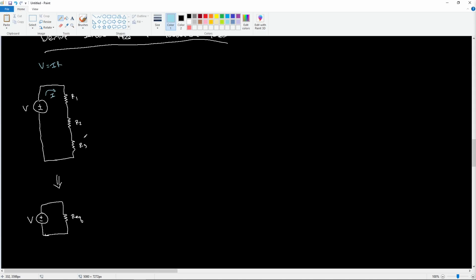And so if I think about conservation of charge, if I have just one loop that I can work through, the current flowing through this resistor should be the exact same current that flows through this resistor, and also the voltage source, right? Because there's nowhere else for it to go. It has to stay contained within this conductive loop.